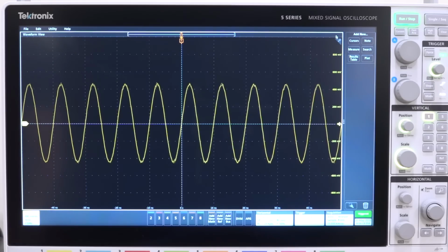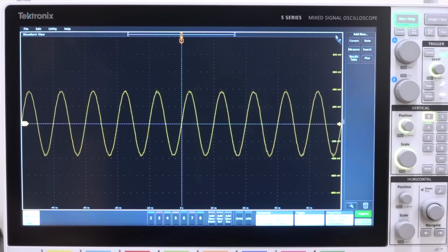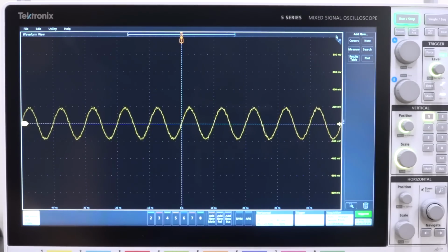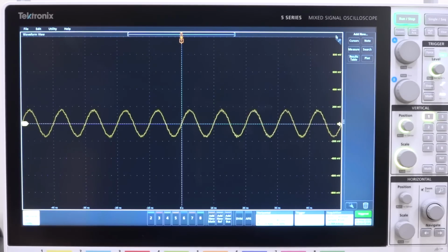But if I change the phase of the two channels and approach 0, you would see this signal diminish as they destructively cancel each other out. So let's go ahead and try it. So I'm going to go down. There it is. There we go. We're reducing. You can see as I continuously reduce the phase difference between them, the signal is going to slowly disappear. So let's just go ahead and enter 0.